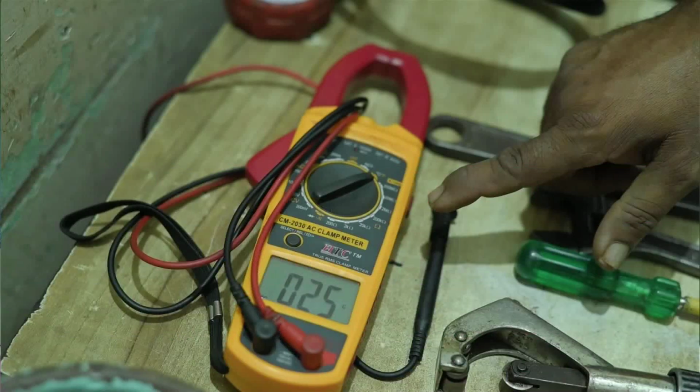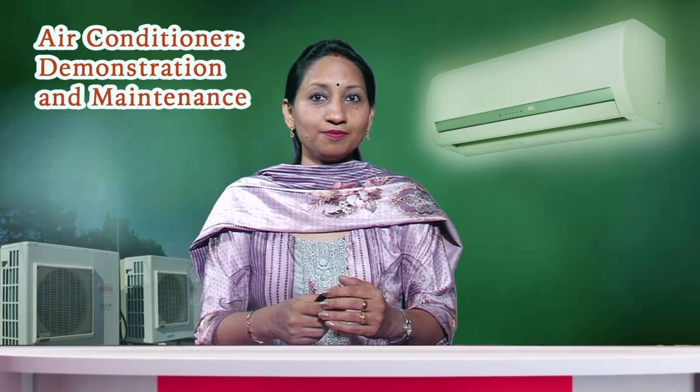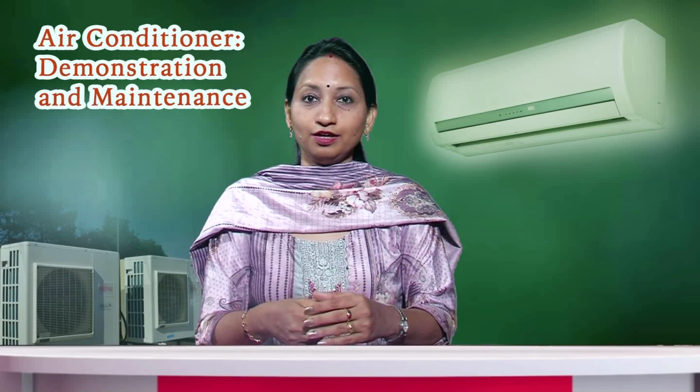Using a multimeter, check the capacitor at the start of each year, as they are not eternal components and can fail often. Capacitors are inexpensive components and have a tendency to fail, especially on the hottest days of the year. Having a backup capacitor ready is a good idea since it is a common AC issue.